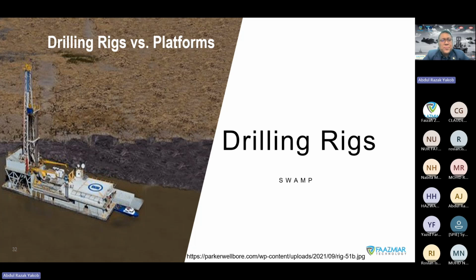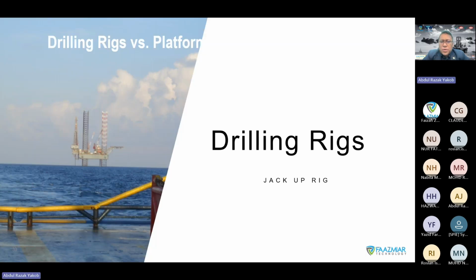So that's the reason why whenever you deal with offshore, you sometimes use a jack-up rig. A jack-up rig is where you have legs, you bring the legs all the way down. Of course, if the sea is very, very deep, then you cannot. For example, at 250 meters we can still go, but anything above that we cannot go with a jack-up. A jack-up can only go about 150 meters, and then you bring down the legs all the way to the bottom of the sea and just land on the seabed. So it can be very complex as well.